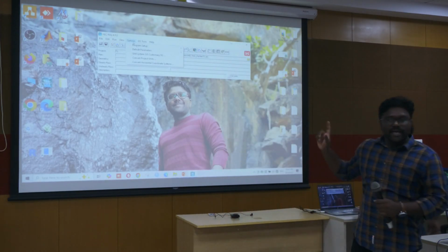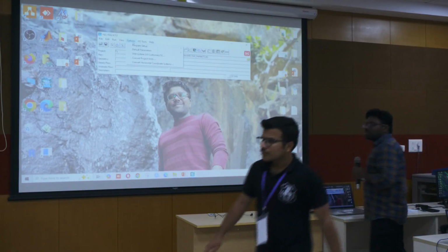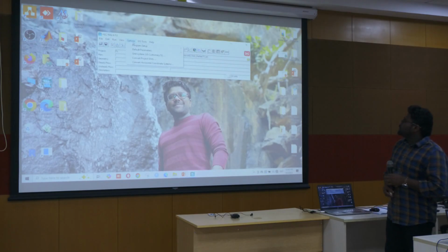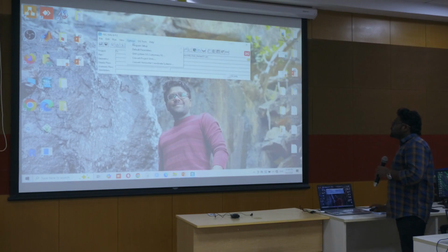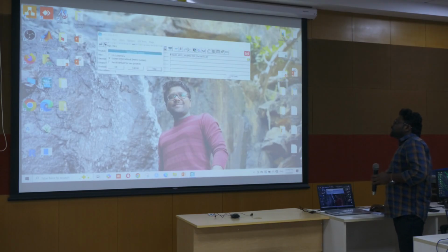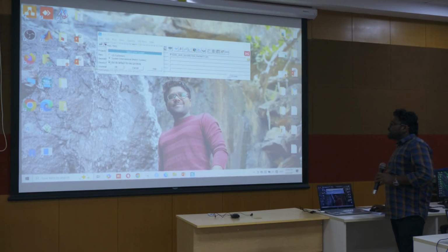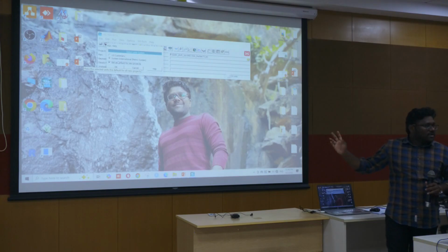So to change it into metric, go to Options. Here the Unit System option is there. Change it to the international metric system. Just click on this. If you select this, next time onwards it will come in the SI units itself. Okay?